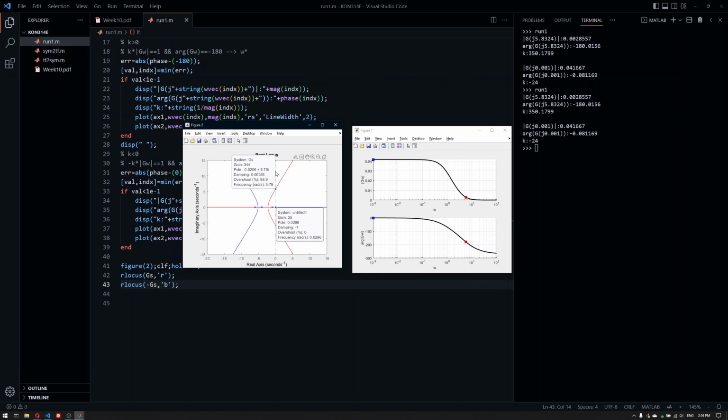So the j omega crossing frequency is the frequency in the Bode plot that we're looking for, because the S domain is projected on the j omega axis if you're transitioning from root locus to Bode plot. So if you plug in S equals j omega, you're projecting yourself on top of this j omega axis. You can only move on the j omega axis if you're on the Bode plot, but otherwise you have more information in the root locus plot.